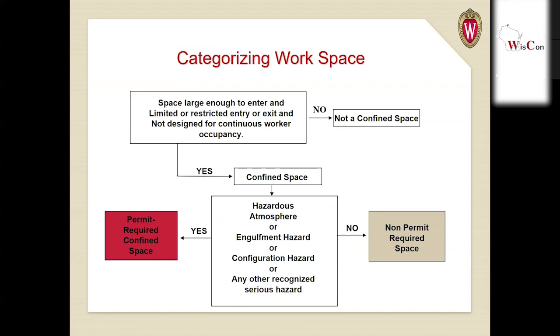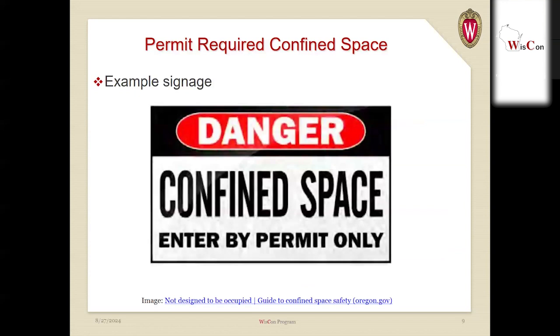Is it considered a confined space? Yes or no? And then what type of atmosphere or hazard does it have? And then based off that, is it permit required or non-permit required? This is an example here of signage that we want to use. And so this would be danger, confined space, enter by permit only.